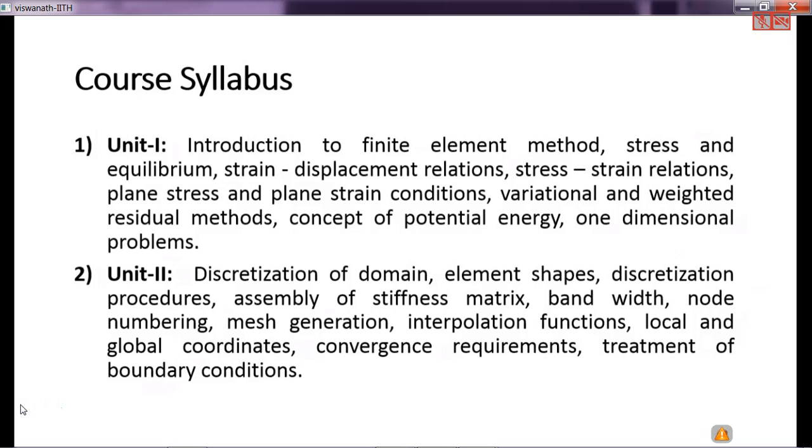Whereas finite element is like a magician. It's like a magic tool. It says that you don't need to have the full thing, but still I'll get you your solution. That's the reason this finite element has been very popular, because it promises a solution in spite of having complex geometries, or you don't know how things would evolve with time, or non-linearities. So one can show that once you write your equilibrium equation from the strong form to the weak form, then you are ready to start working in the finite element sense.